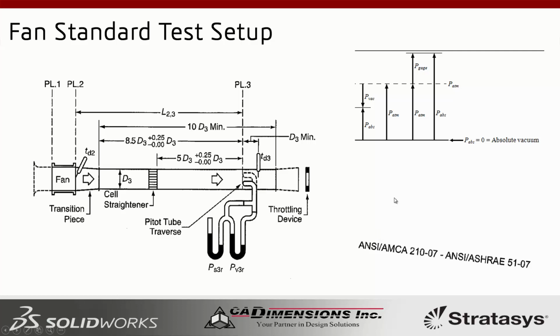So let's go over this setup real quick, just to give you a better understanding of what we're looking at. This is where the fan that you're designing will reside. It will sit right here. This is a nozzle where the air is being sucked in. As the air flows through your system, typically there might be some turbulence. The air might be non-uniform, and that is the purpose of this cell straightener right here. What this does is straighten the air out.